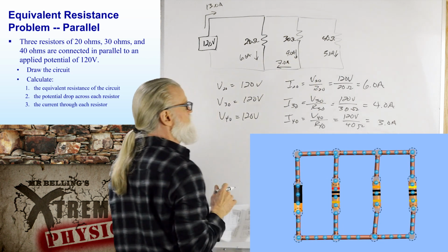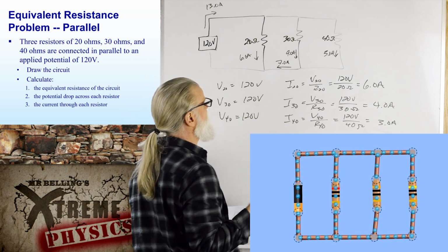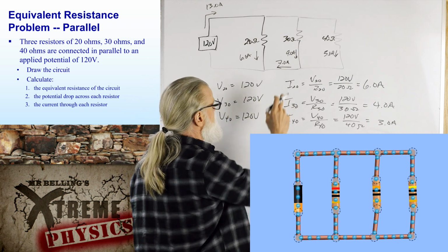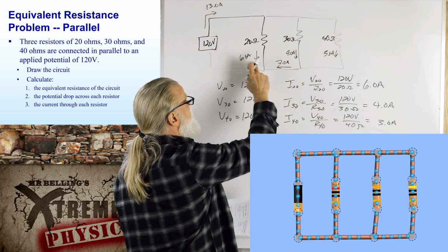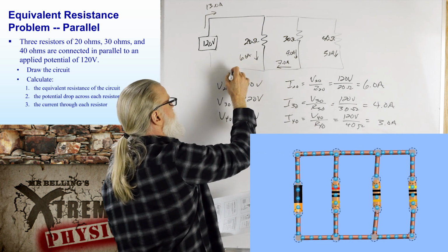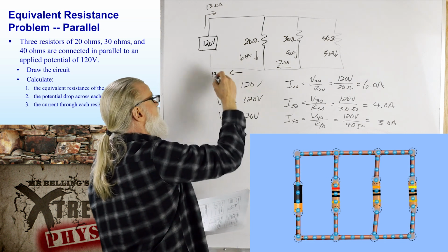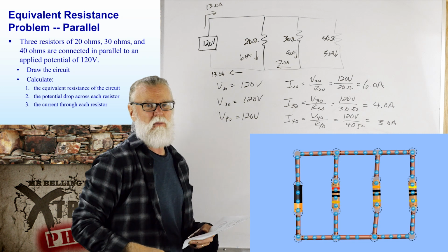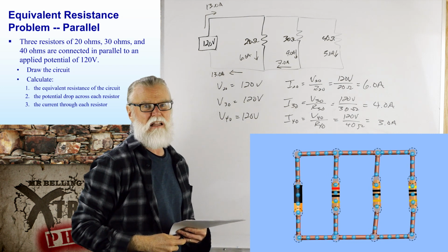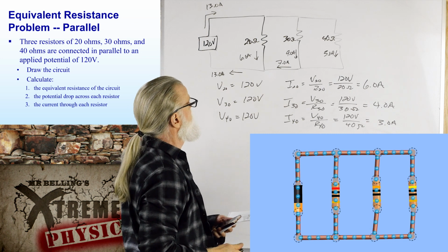The current in must equal the current out because it's just charges flowing. And then we have 7 amps coming into this junction and 6 amps. So therefore 7 and 6 is 13. We must have 13 amps flowing through here. Oh, and that's what we calculated before. Beautiful. It all makes sense. It's all coming together nicely. All right, so there we go.